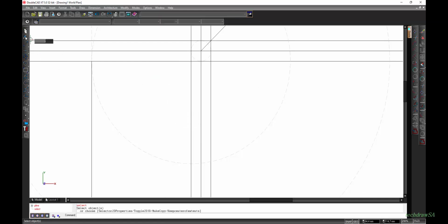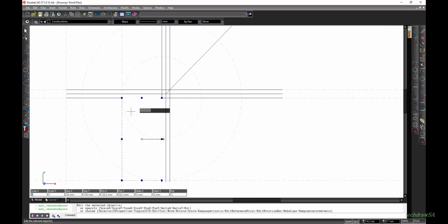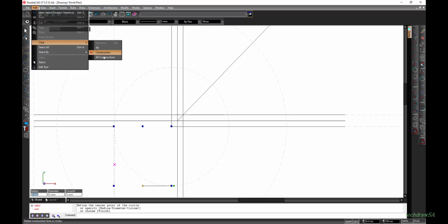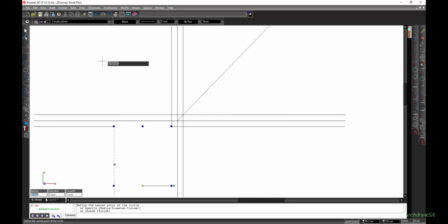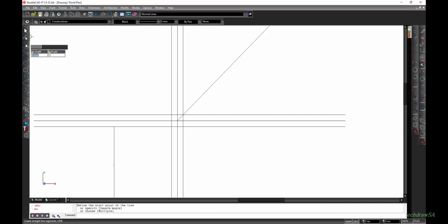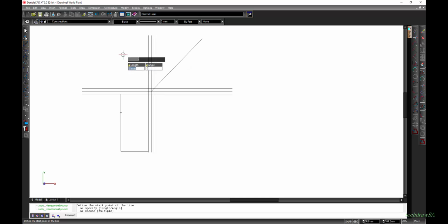And now if I use the selector tool and I click anywhere on that line, you will see it selects that rectangular box. Now at this stage you can actually clear all the constructions. So we can say edit, clear, and all constructions, which will clear only the constructions, not the whole drawing. And if you escape out of it and you go back to your line tool, you will see that you have your solid outline of that rectangular box.